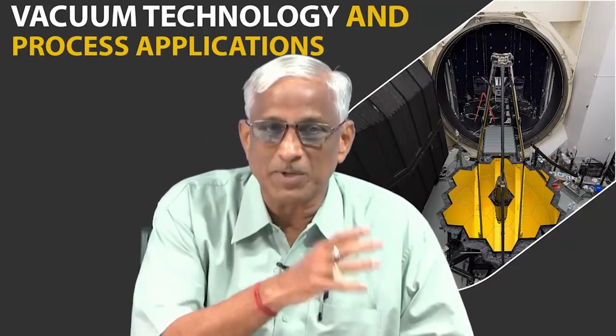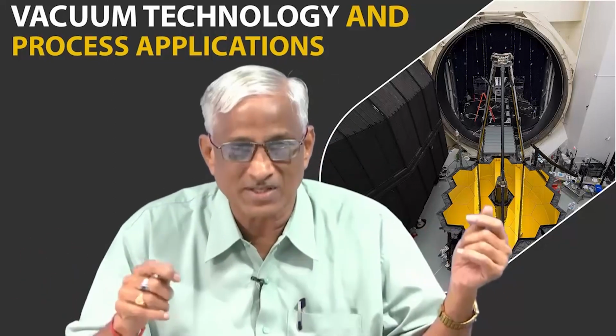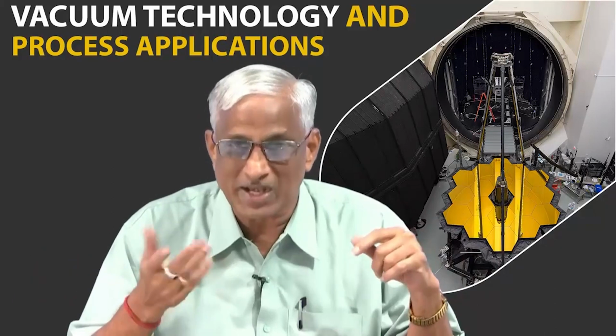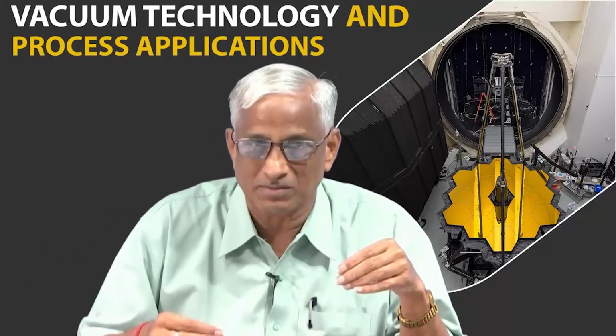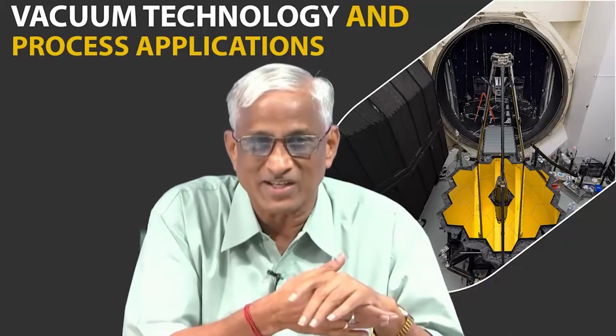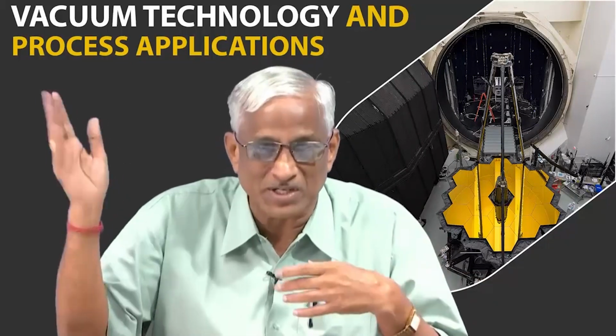While you are testing for the ultimate vacuum without any process, you should concentrate only on surfaces, chambers, welds, etc. But later you should also give a process-equivalent load, because the process will not be there at the manufacturer's site. You can let in some pure gases to represent the load.